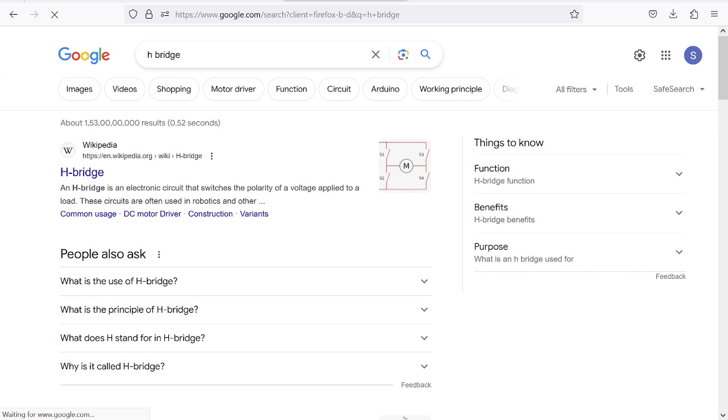Oh, there is some mistake here. They have asked for switches 3, 4. So this will not be 0.67, this will be 1 minus 0.67, which is 0.33. So 0.33 divided by 10 to the power 4. So this will be 33.3 into 10 to the power minus 6. So it will be 33.3 microseconds.